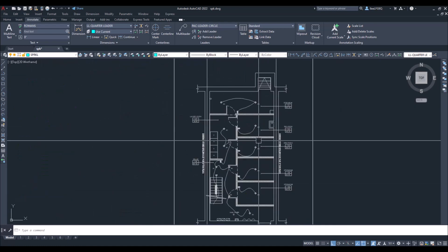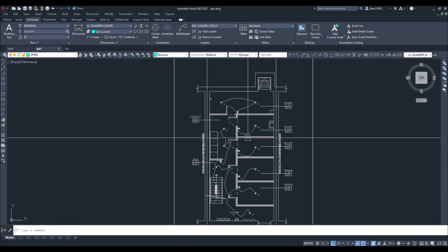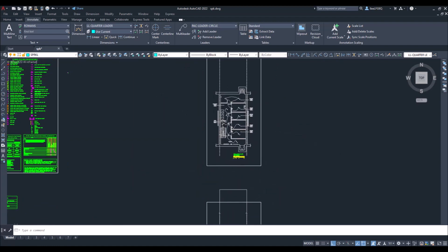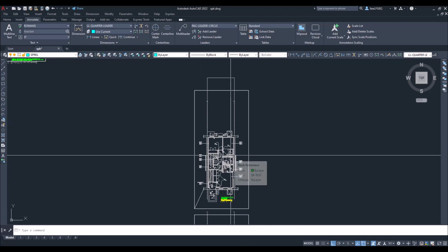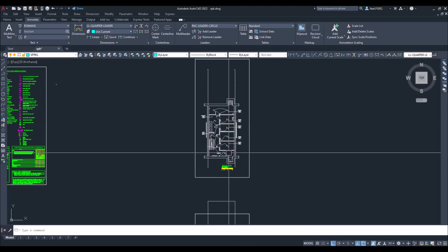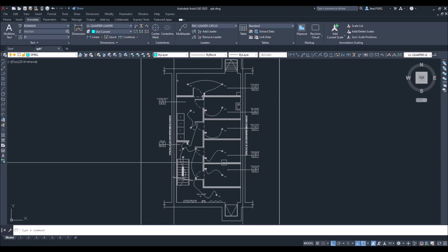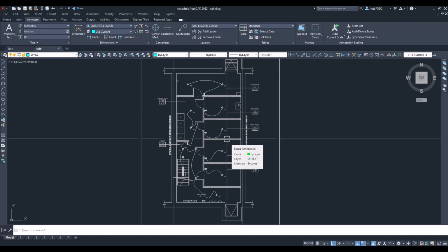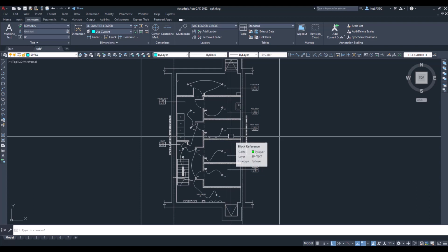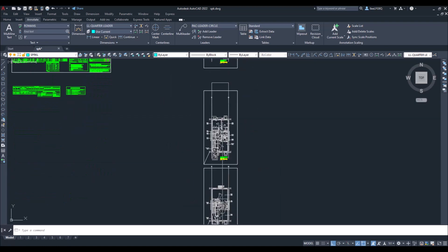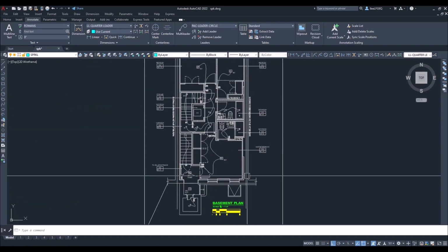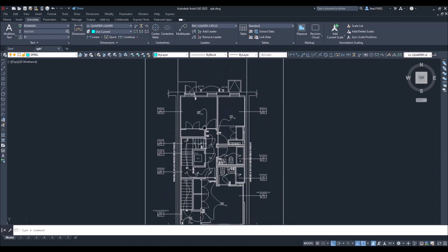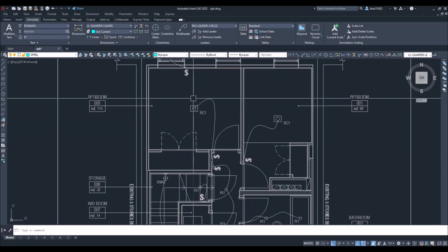So the first step is to lay out the sprinkler heads. And to do that, we're going to have to consider what type of ceiling is going to be on each floor. So in the cellar, in this example, is not a finished ceiling. So we don't have any sheetrock ceiling. It's all going to be exposed. So in that case, we can use upright heads. So typically we use upright heads in an area that is not finished, where the appearance is not that important. And for the upper floors like this, where the ceiling is finished, we're going to try to give it a cleaner look by providing concealed sprinkler heads.